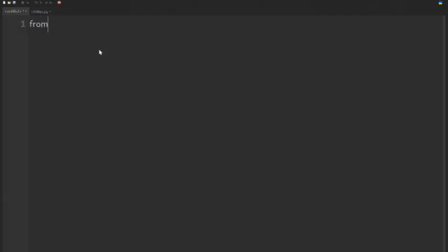At first, we'll be starting by importing the libraries. From utilities, import star. If you keep import star, it will import everything inside the library. And import time. We are importing the tools we need. This function moves the ultrasonic sensor to the left and right to check which side is free. And now we are starting a function called scan direction.